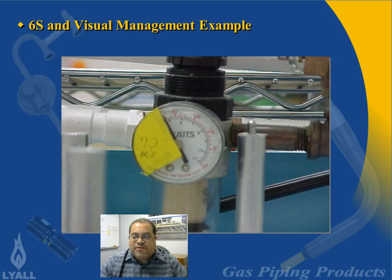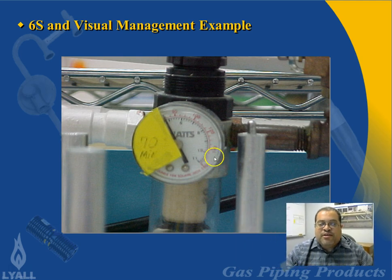Okay, so here's a couple of other examples, and some of these are going to be kind of random, but here you started out with a dial indicator. But what do you have when you have a dial indicator? It doesn't really tell you that much. So you have the dial at a certain setting. How do you know what setting it should be at? So in this case, this visual indicator was developed by showing an acceptable range. So it not only has the number of what the minimum pressure rating is, but it shows an acceptable range. And if it's outside the range, presumably you have to stop what you're doing and address something.